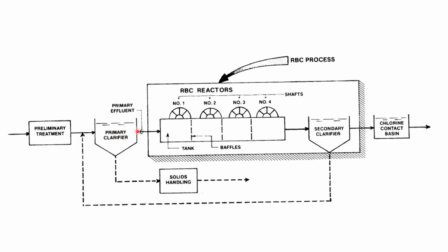We get the effluent coming off the primary clarifier, and we have these tanks here in series, with 4 RBCs, and they just rotate and rotate, and the wastewater gets moved through here, and those bugs or microbes on the film of those plastic surfaces are helping metabolize these wastes as well.